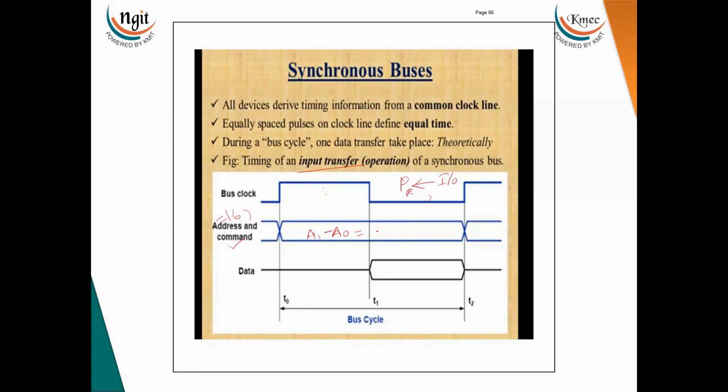So here we have to write the hexadecimal number. Now if I say 1423 X, this is my address of this bus. Then how to write this one? The binary equivalent of 1 we have to write is 0001, and 0100 is the equivalent binary value of the 4, 2 like that.